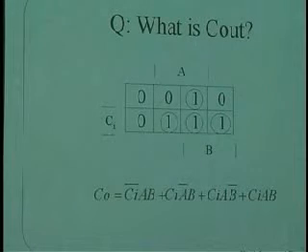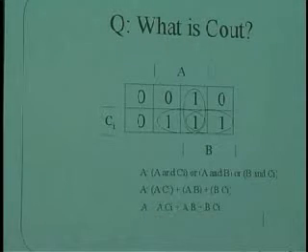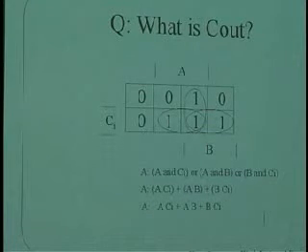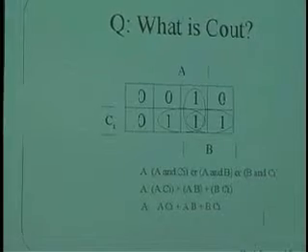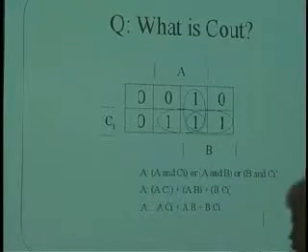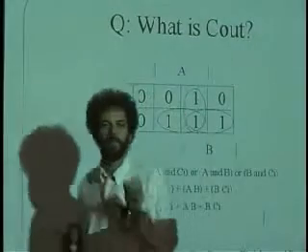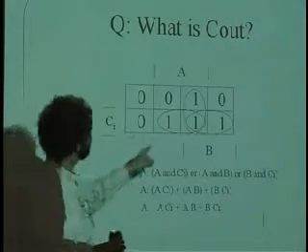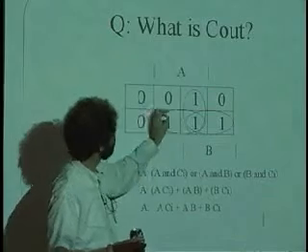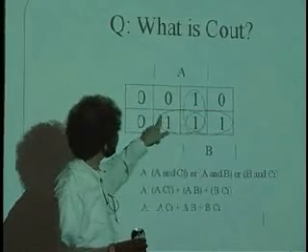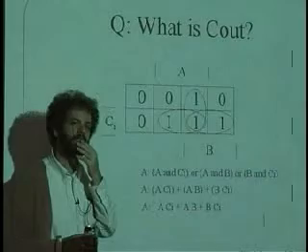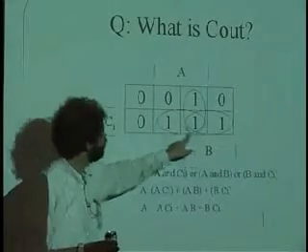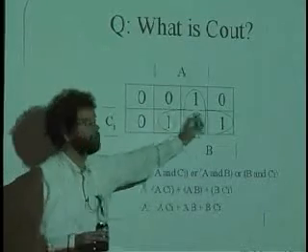So that's nice. But it turns out that we can do a simplification on this K-map, which is identical to the very difficult simplifications that you guys did in the discrete math course. We can make these circles bigger than one square. What we can do in particular is I can take these two ones that are near each other that used to have a circle on each one, and I can circle both of them. Now what does it mean to circle both of them and to make only one product term out of this oval here instead of the two product terms that I used to have?